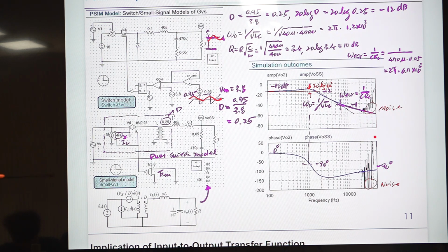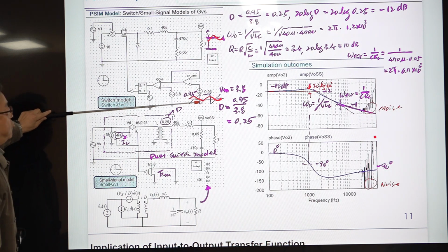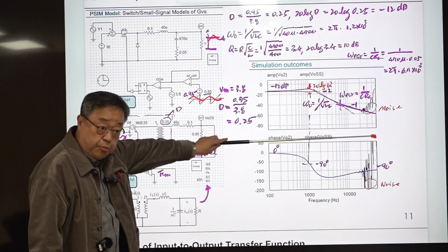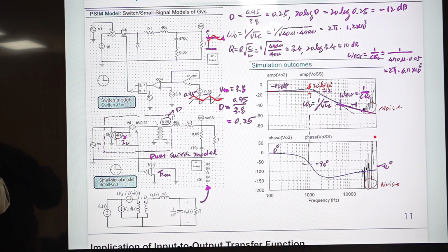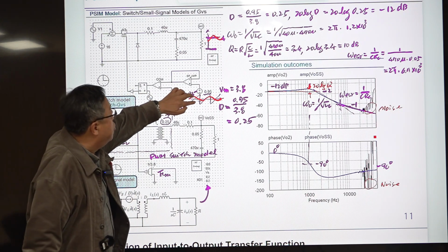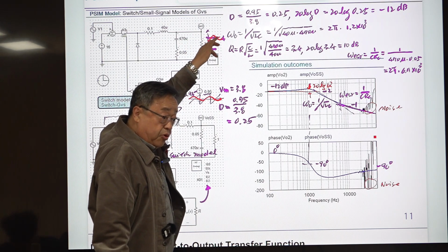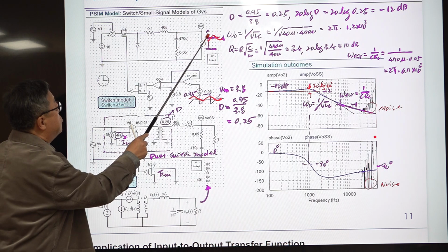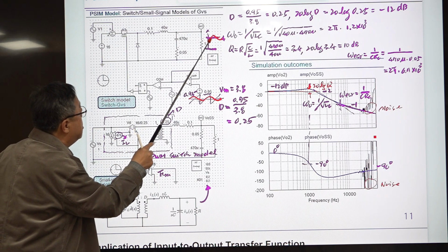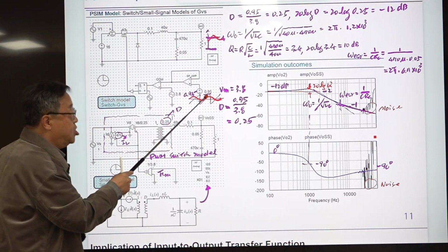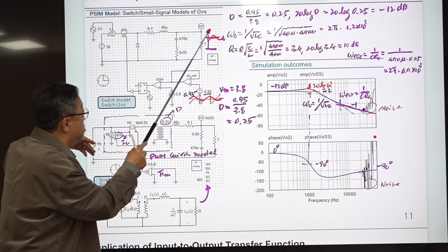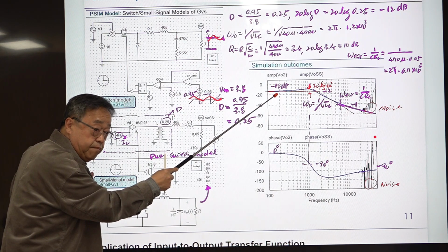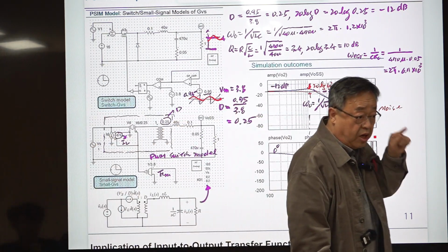Okay. So with this, you can plot this. This is the plot of frequency response. The frequency response is the response of our voltage due to the sinusoidal variation in the input voltage. So the magnitude of this can be input, and the magnitude of this is output. From this simulator, it's just extracting this sinusoidal component of our voltage, and it compares the result with this and evaluates the ratio between the magnitude of this one and this one, and puts one dot here. That is called sinusoidal response at a particular frequency.